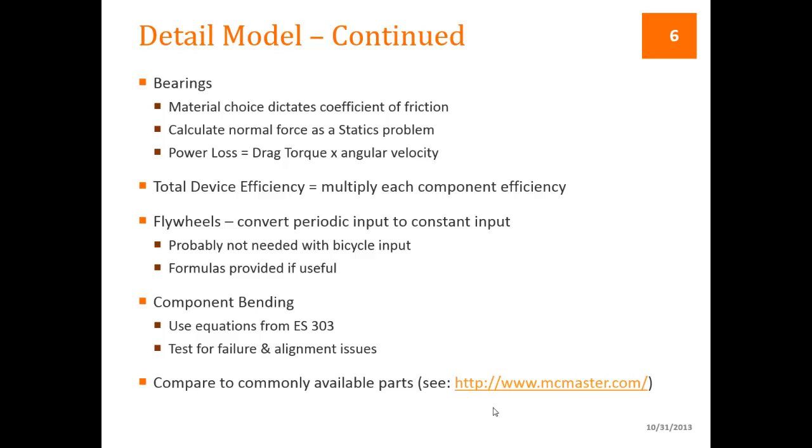And so picking a shaft that's a quarter inch instead of 0.253, for example, will allow you to buy your shafts more easily and therefore more cheaply, if you can get away with a quarter. If not, you might want to size it up to the next standard size instead of picking this strange size, even though that might be the optimal one that your model is telling you.